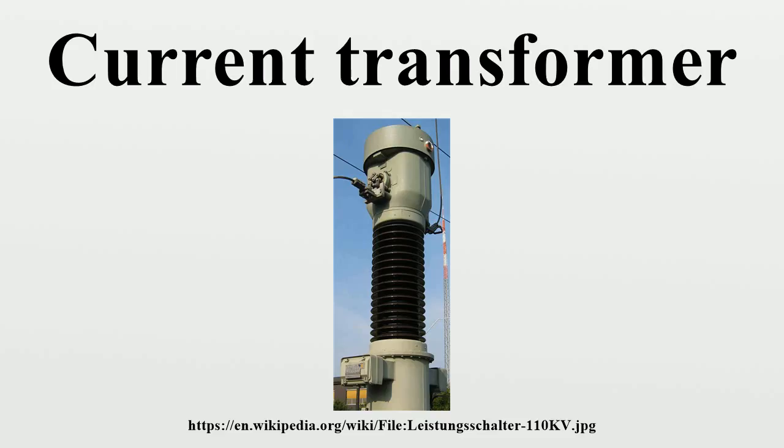Sometimes a section of a bus bar can be removed to replace a current transformer. Often, multiple CTs are installed as a stack for various uses. For example, protection devices and revenue metering may use separate CTs to provide isolation between metering and protection circuits, and allows current transformers with different characteristics to be used for the devices.